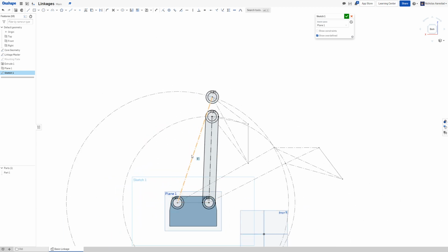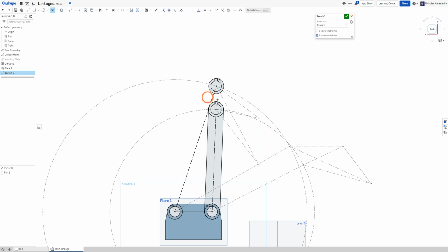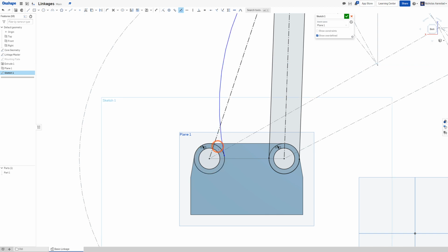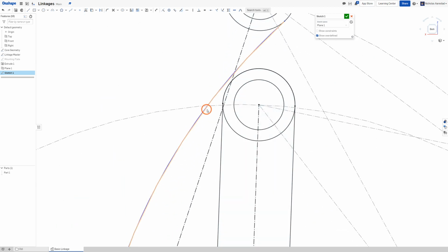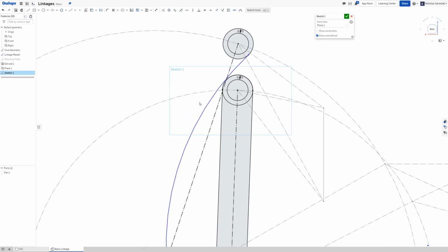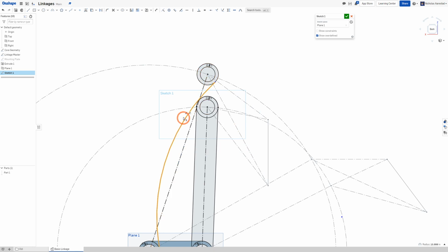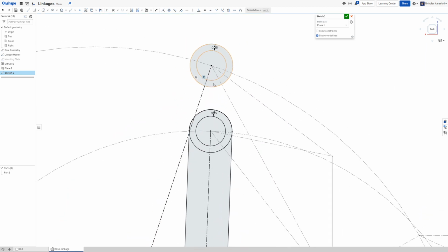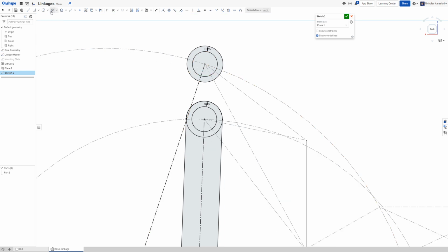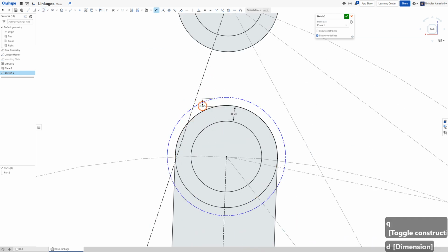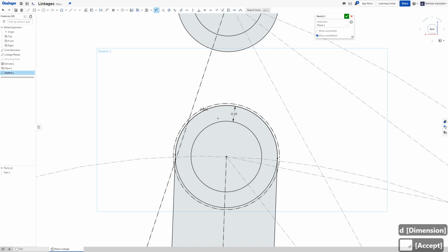This one, though, we're going to need to be a little bit clever and use something like an arc. We'll take that and make it tangent here. This isn't totally necessary. So the other way to do this is instead of using that arc, what we could do is really small offset circle here, say 32nd of an inch.